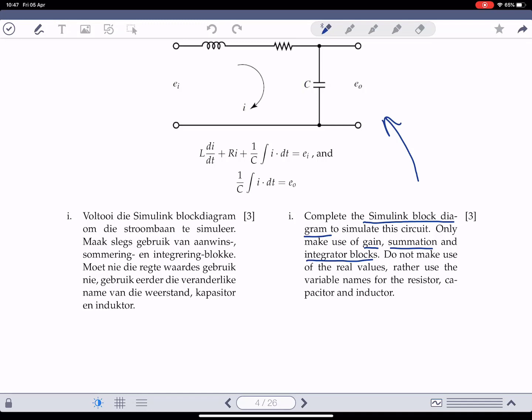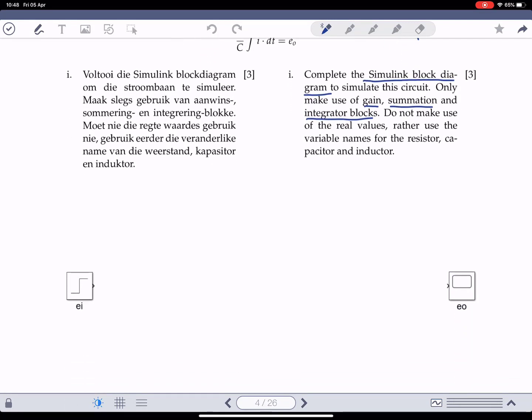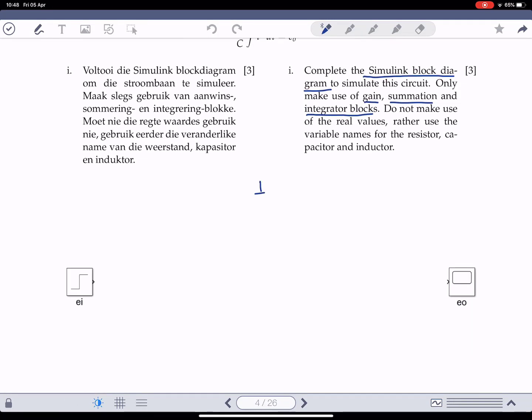integrations, and this is the simplest way to do it. Here we can identify that component there, that's the integral of the current, there is the current, and there is the derivative of the current. So what I can do immediately is drop an integration and another integration. Remember, integrals can be depicted in the Laplace domain by 1 over s.